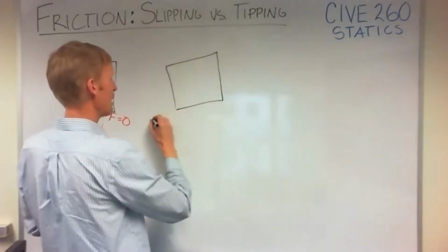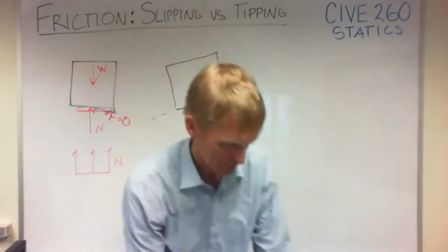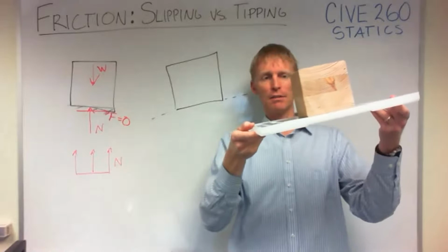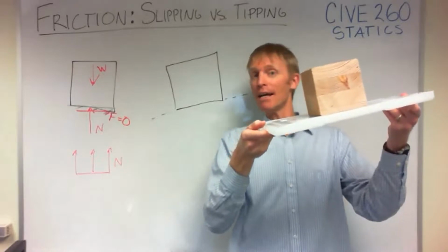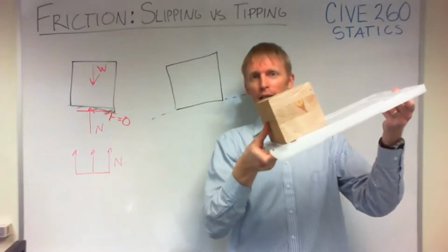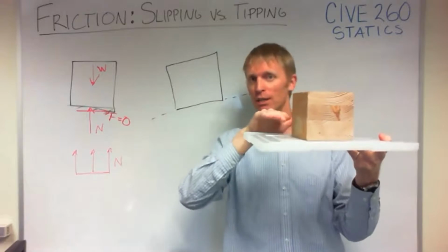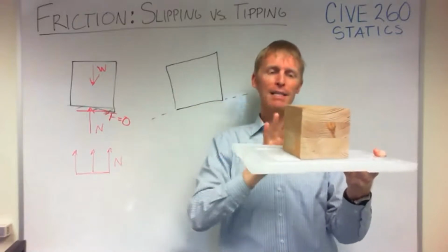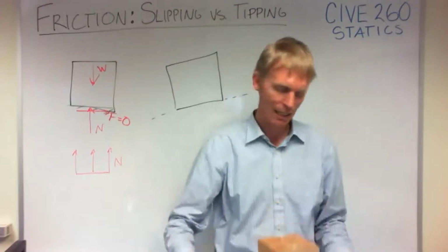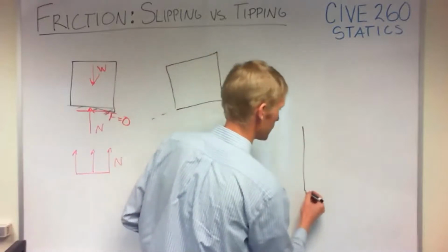We're tilting now, let's put dotted lines for my surface, tilting this surface. So here's my block. I start to tilt the surface. The block doesn't slide yet. But as we go a little further, a little further, a little further, oh, there it slid. What we did there is we actually reached impending motion, which is when it started to move. And it actually went from engaged friction, but not impending, to kinetic friction. Let me draw a graph of that over here in this corner.